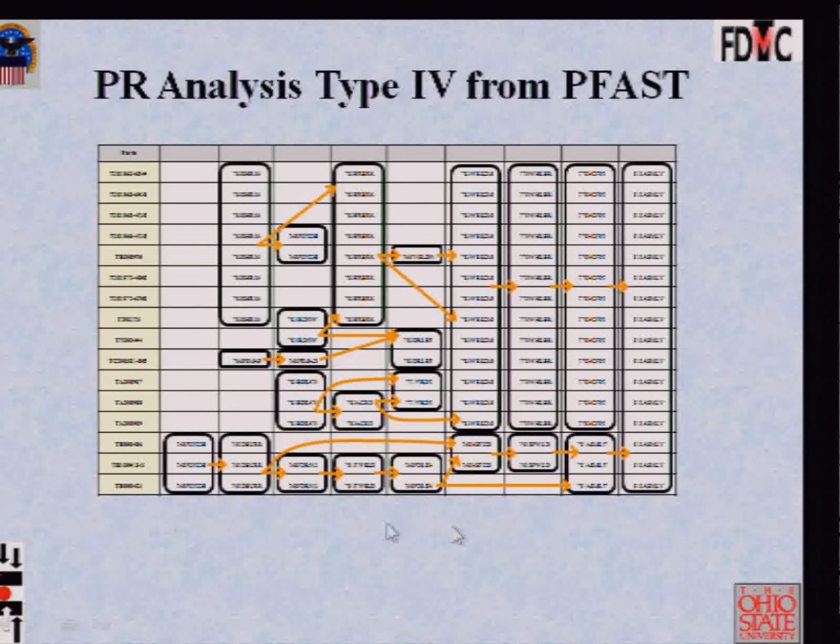This would be maybe one family of parts, this would be another family of parts. Please, you are not going to get these clean families of parts, especially when you have expensive equipment or monuments being shared across different families. But again, being able to visualize in entirety the complete coming together of all the value streams at any level, component, sub-assembly, main product, that's the beauty of value network mapping when you work with bills of materials and classical industrial engineering charting methods, and of course, software.